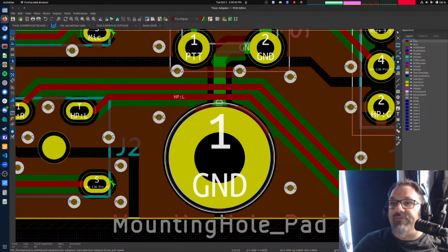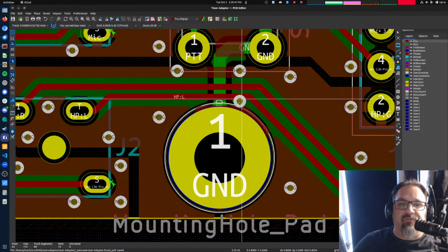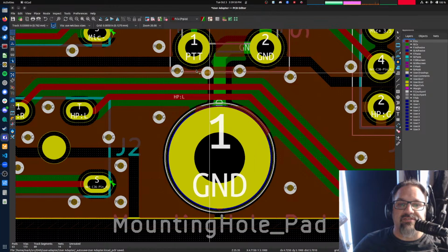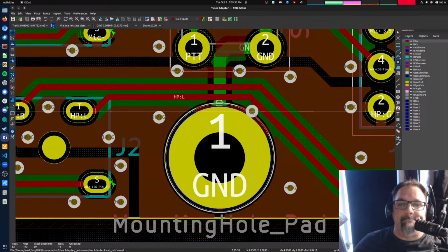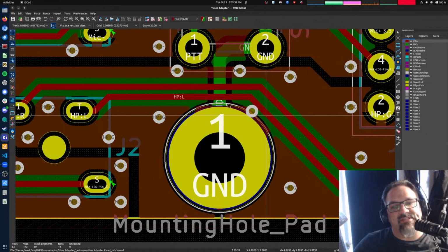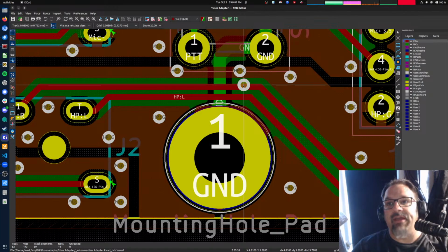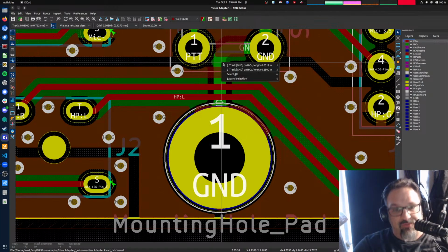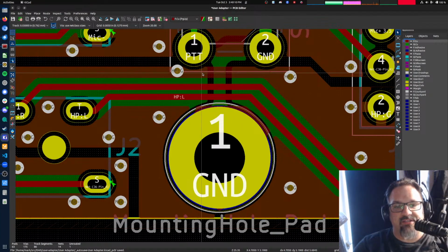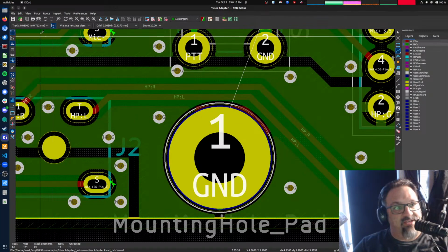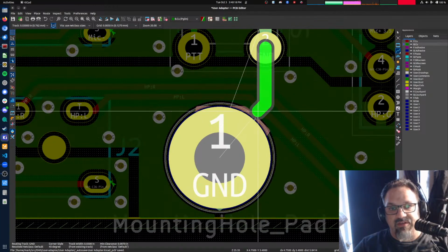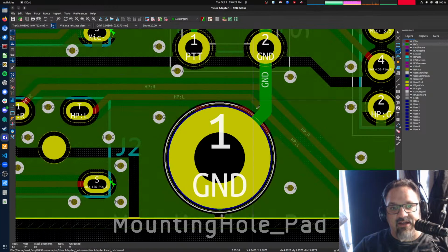From pin 2, then 45 into the mount hole would be a smooth extension of the ground line. Because when you're doing 45s over this, it gives you less space for... but I see your point because that will allow me to use that for ground. Okay, so Nerd Garage is pointing out the stupidity in my way of running that there, which is what's causing this problem of not being able to get a good solid ground across. If I were to instead do this, then I can...